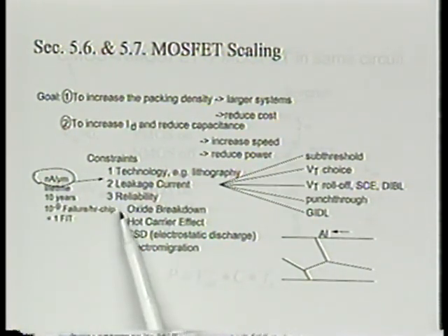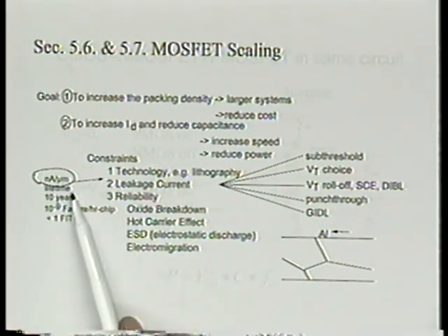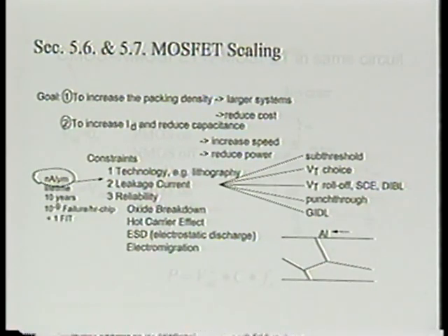The concepts related to reliability will be things like lifetime. You can say you want to guarantee a lifetime of 10 years. But that by itself is not a meaningful thing, because no one can guarantee absolutely no failure. You may guarantee a failure of less than this much percent in 10 years. This brings us to something called the failure rate.